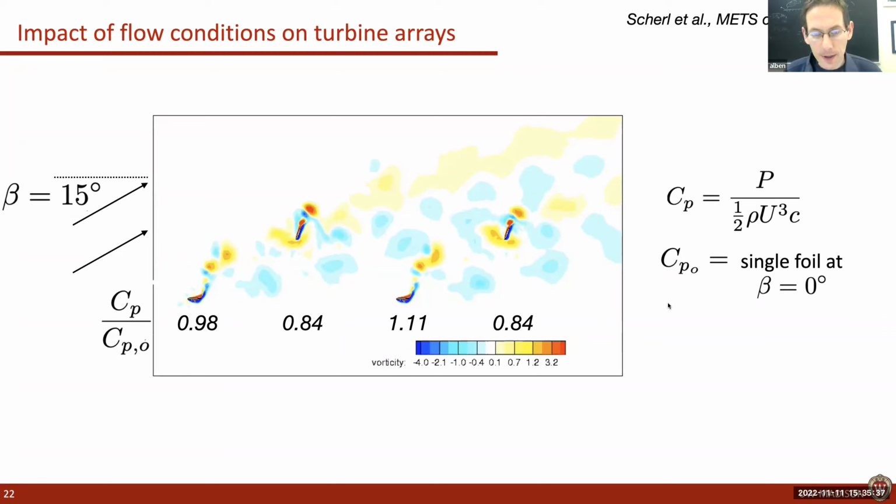Is this from a simulation? Yes. So you covered this whole space with finite elements or something? Or? Yeah, so it's through the dynamic meshing. So each one of these foils is moving the mesh, and then we're just recomputing the location of those new points. So these simulations must take a long time. Yeah, it's still 2-dimensional, so it's not too bad. This is a 2D simulation at Reynolds number 1000, so it's not that bad.